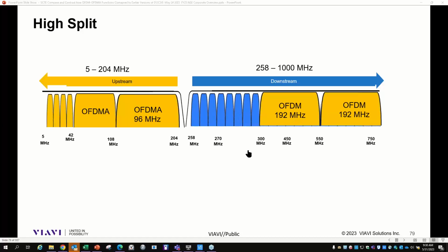I do have some customers who have completely removed all of their digital video carriers now and are completely all DOCSIS and have deployed their second service group as well. And that's why your meters today have multiple MAC addresses. They need to be provisioned in order to do DOCSIS testing. So you'll be able to do service group 1, service group 2, et cetera, right?